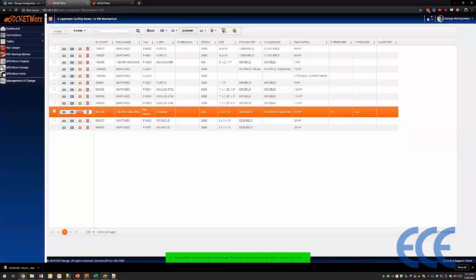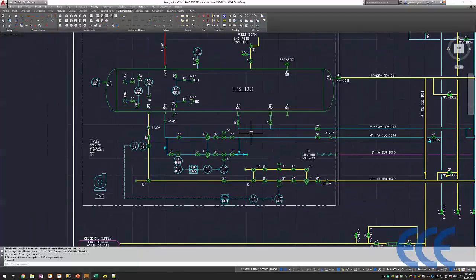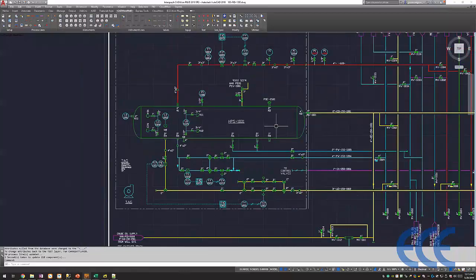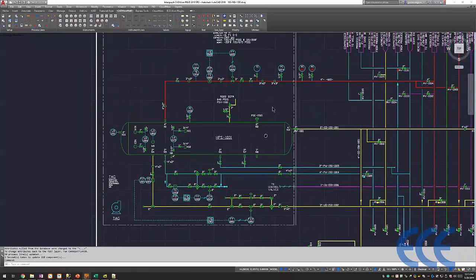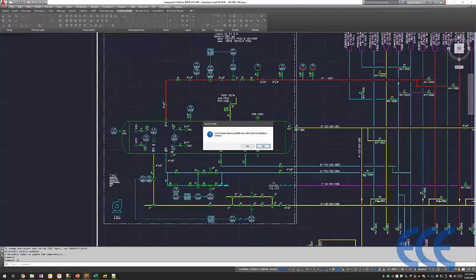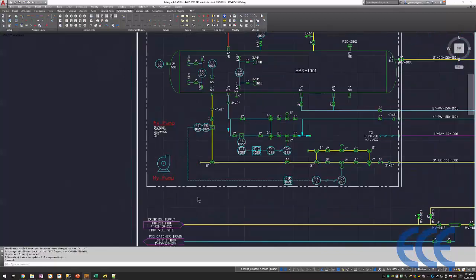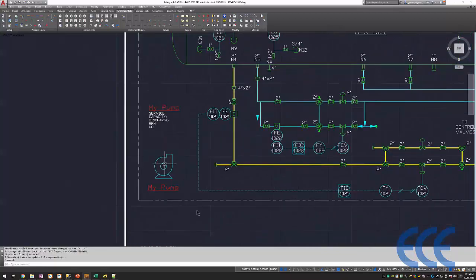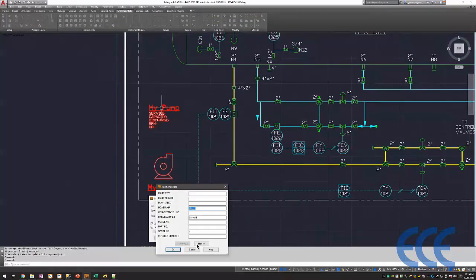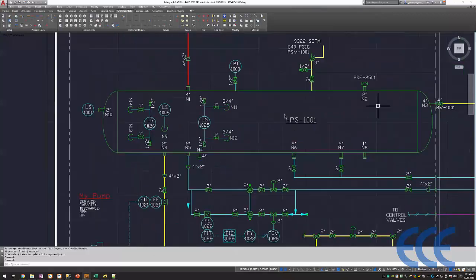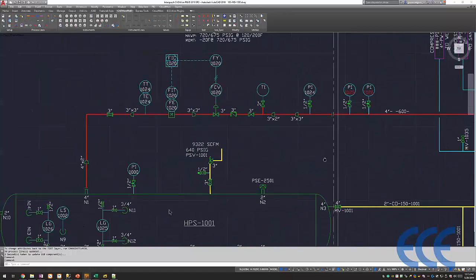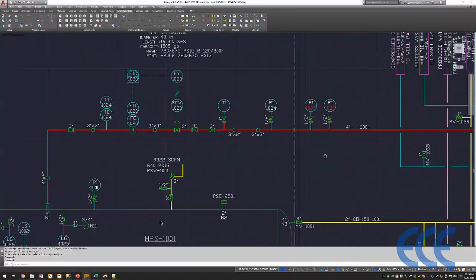Cool. So from here, what we've kind of demonstrated is just the ability to control your data from datasheet records, basically. I'm going to go back to the P&ID, since I did some modifications on the data side. So now all I have to do is just sync on this side, and I should be able to see those same records here get updated, right? So here is my pump. I can see the data that I filled in here, the manufacturer, the power, the serial number, and so on. And the same thing for those PIs. So those two PIs I added, that additional data came in exactly as I had applied it.